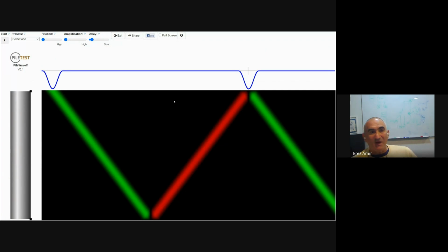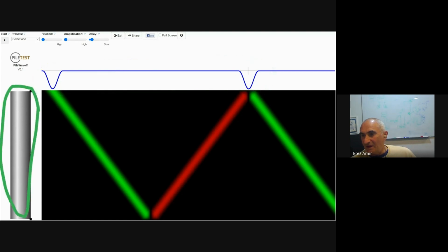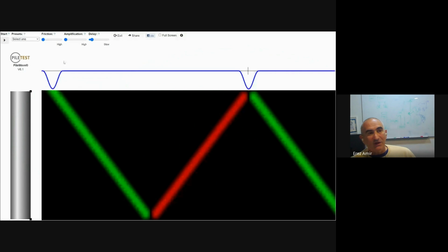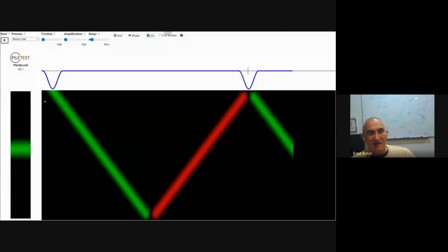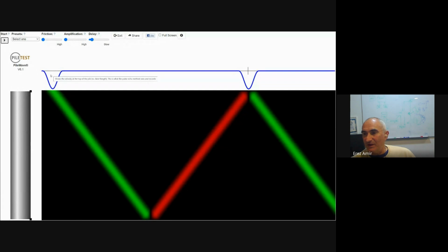Okay, so that's Pilewave. Basically, what we see on top is the reflectogram, just like we see in the PET window. Here we see the shape of the pile, and here we see some kind of a representation of what's going on with the waves. We can draw a pile shape. This is a simple cylindrical pile. We just click Start, and we can see a pressure wave followed by a tensile wave, and we see the head, the hammer impact, and then the reflection.